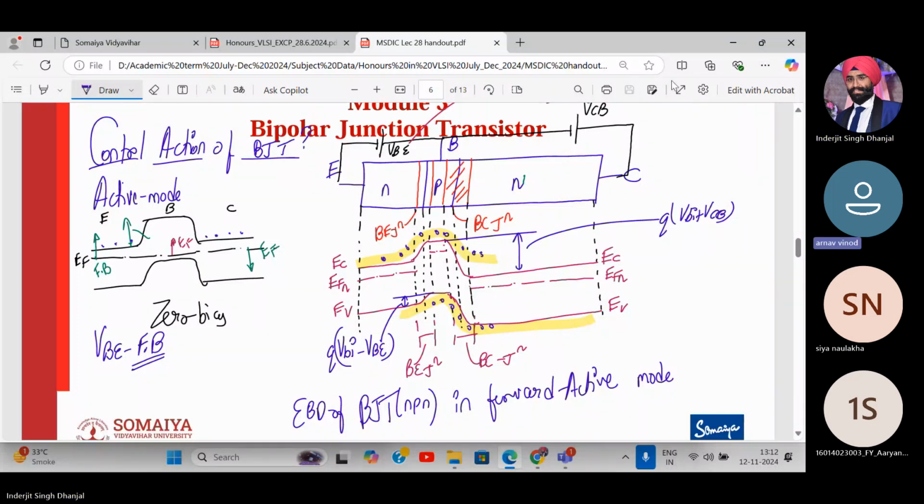Very good. Which Fermi level is this? This one, right? In the diagram, this is EFP. No, see, this is EFN, just on the N side. This is EFN of the N side again. What is happening is, instead of a negative voltage, you are applying a positive voltage over here. So positive voltage will pull the Fermi level down. And why will this Fermi level go up? Because you are applying a negative voltage. And why will this Fermi level go up? Because you're applying a more negative voltage. When we apply negative voltage, it increases the electron energy. It rises to a particular level.